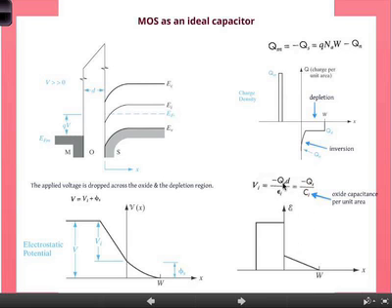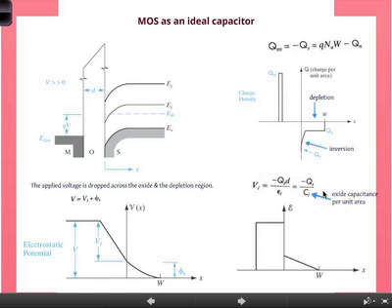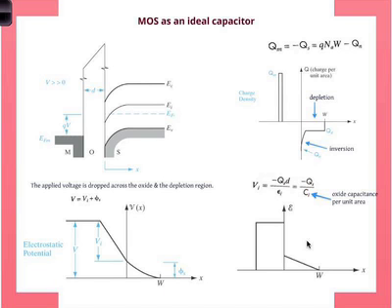We know that there will be some capacitance associated with the charges here as well, because we saw that for the p-n junction. So this is only one part of the capacitance. So you have one more term of the capacitance, which we'll talk about next week. But you can think about this oxide capacitance per unit area as the charge storage capacity of the parallel plate capacitor, ignoring the semiconductor, essentially.